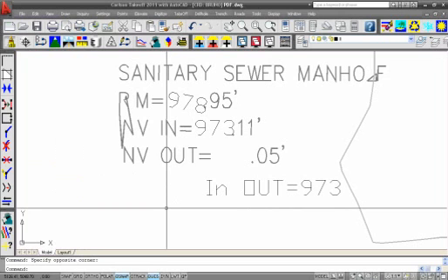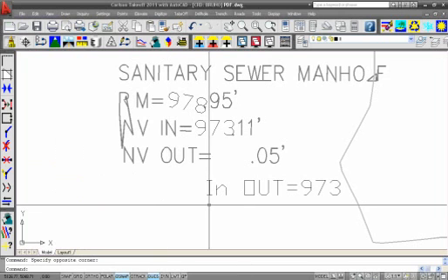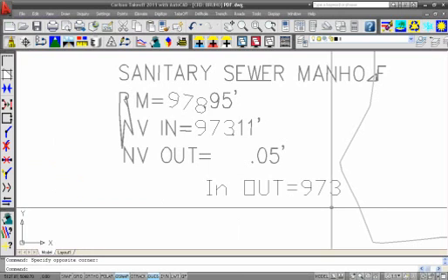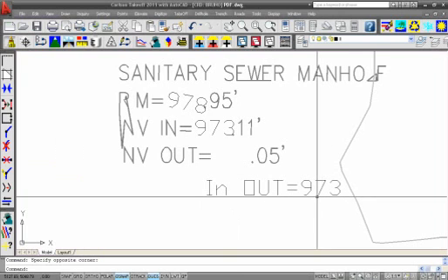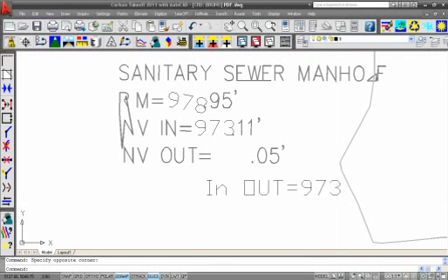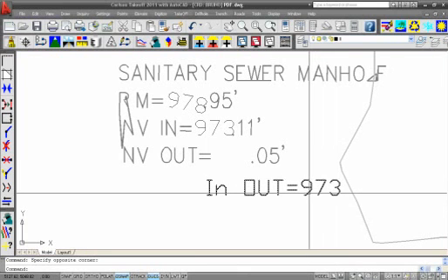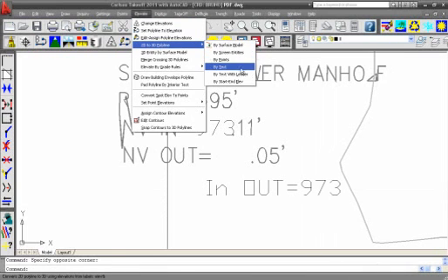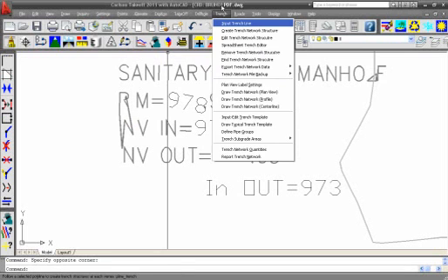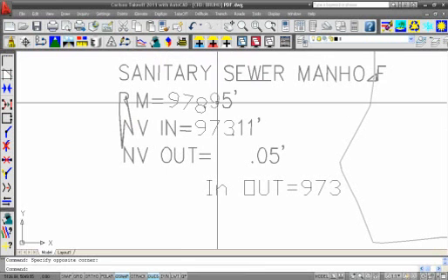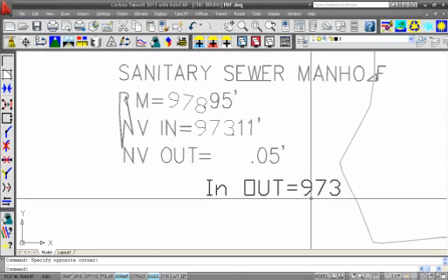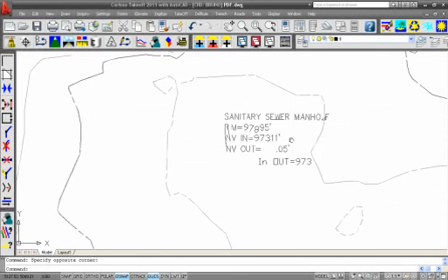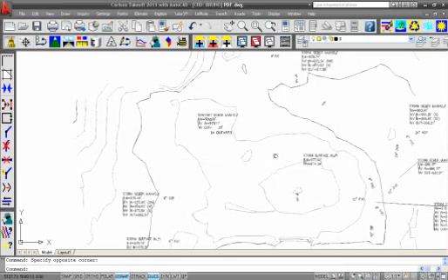So, yeah, say we had a lot of leader lines for a 3D line or a curve, we could convert all those leader lines into actual text, and then run Elevate 2D to 3D by that text. Whereas before, that line work would just be dead to us. So we now have the ability to work off of that line work and convert it in the drawing.